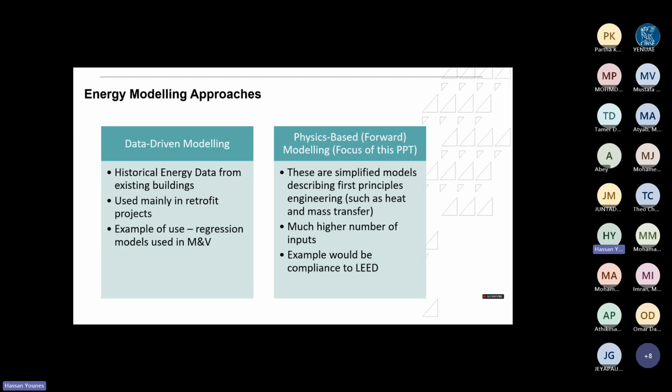And that is typical if the building has its own chillers. If it has district cooling, then you'd look at the district cooling bill and you'd see that as the temperature outside increases, as the enthalpy increases, so will the energy consumption. You can build this model with one or multiple variables. We try to get to linear modeling when we do data-driven modeling. If you look at chillers in particular, it might not be of the order of one, and it could be multiple variables as well. But for buildings, we normally go with linear regression, and it would involve one or multiple variables.